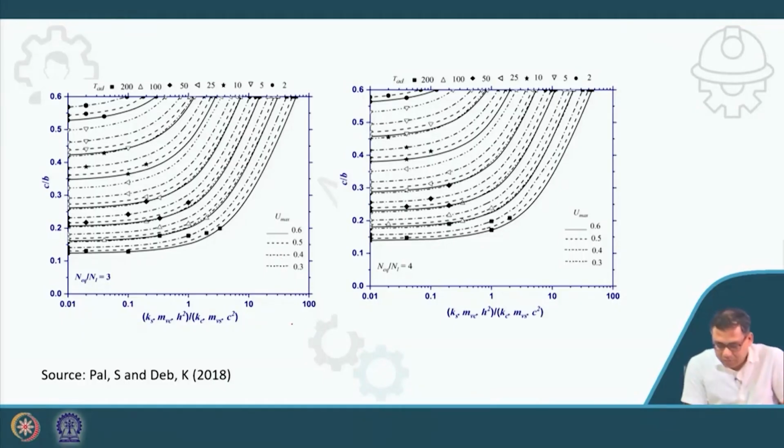You know, an RU value of 1 means that liquefaction is initiated. But definitely we will not design for RU equal to 1, because then the liquefaction will occur. So we will design it for a lower RU value with some factor of safety. That's why generally in the field this RU value, or U_max value, is taken as maximum 0.6. That is the design value.